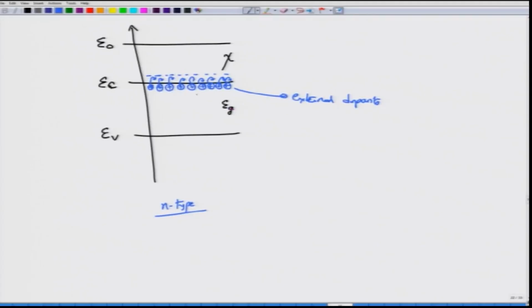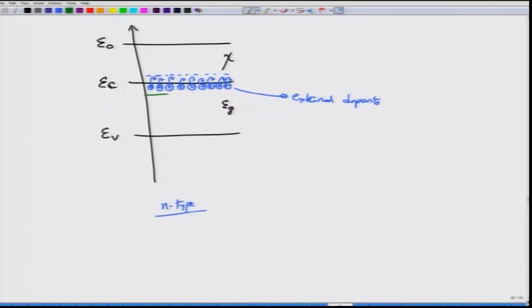Okay. So, now what happens to the Fermi level? Remember, Fermi level was something that would tell you how the electrons are occupying. Now, there is an excess electron density compared to the pure semiconductor, there are excess electrons in the conduction band. So, which means that the Fermi level cannot be located in the middle of the band because above the Fermi level there are electrons. So, therefore, you need to move the Fermi level up, and the Fermi level moves up and becomes very close to the conduction band. I am exaggerating this, but in practice this EF is so close to EC, the difference between EC and EF in the n-type material when you have doped sufficiently is just about 50 milli electron volts.